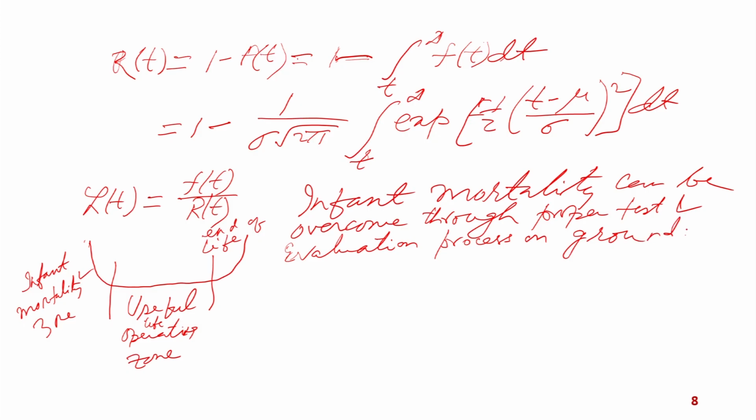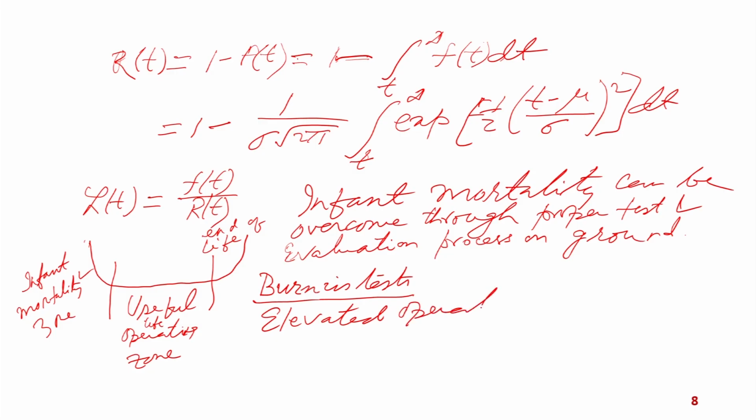Generally the electronic components, like the integrated circuits and a few other electronic devices, are prone to this infant mortality. So, what is done is a burn-in test. What is a burn-in test? Burn-in tests are performed in elevated operating conditions.